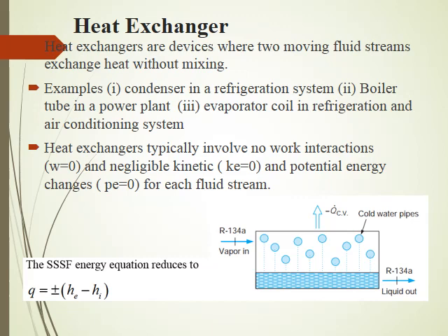Now heat exchangers typically involve no work interaction and there is negligible kinetic energy change. Moreover, there is no significant potential energy change for each fluid stream. The heat transfer rate associated with the heat exchanger depends on how the control volume is selected.